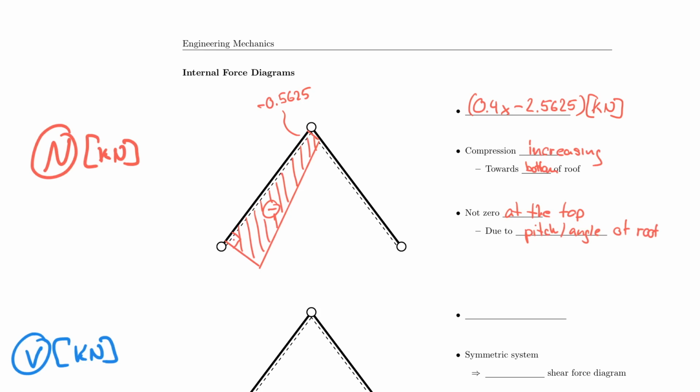In fact, since we understand that the left side pushes on the right side and the right side pushes on the left side, we are probably able to draw the diagram for the right part now, which is very similar, and you hopefully understand that it is also in compression, so therefore it must be negative on that side. And then it is also negative up here on the top. And then I can connect the dots again and close my diagram, which now looks like this.